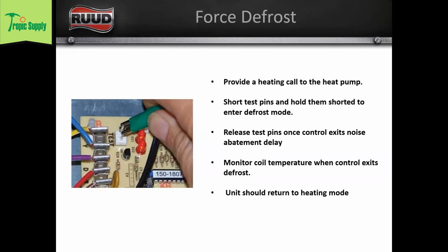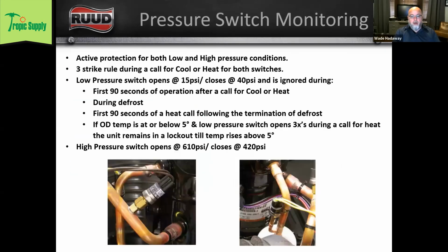Wait, we got a couple of questions on the pressures. Yeah, okay. Somebody is questioning that 15 psi is too low on an R410A system. Can you discuss the low pressure settings on that a little bit?